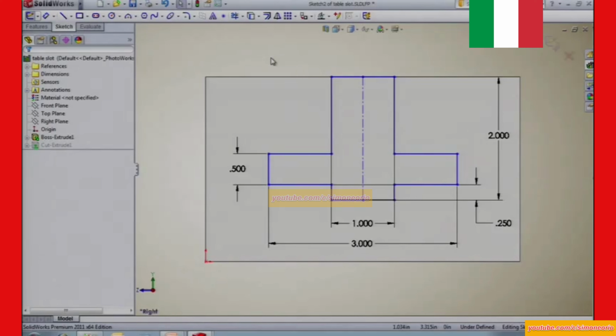But it'll link with the other ones in the part, right? And the link is a one-way street too. If you put it in your model and it's linked to the library, the only way it's going to change is if you edit the library feature part. The only way you can edit it, and we're going to do this shortly in the part, is you have to break the link. If it's linked, it says go to the library and get it and bring it in.